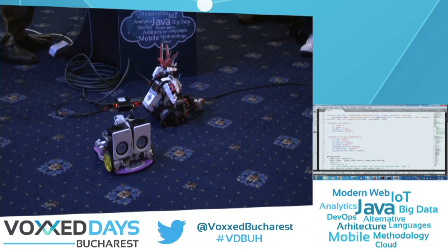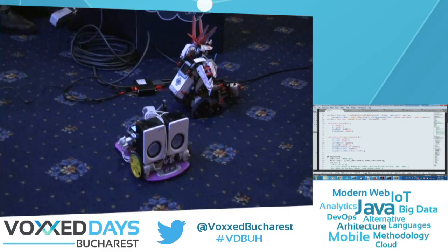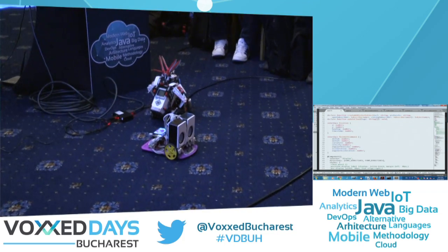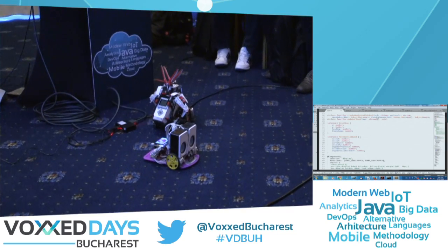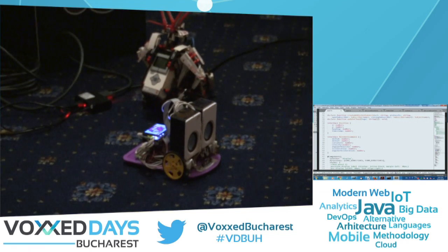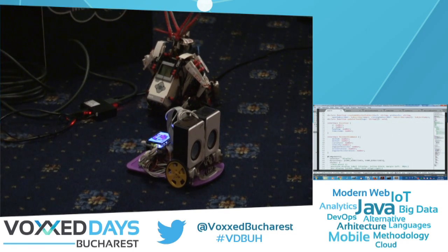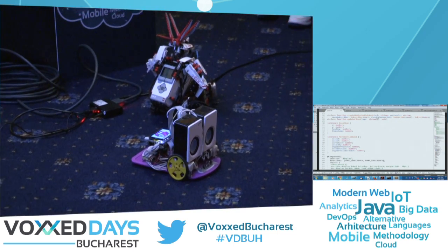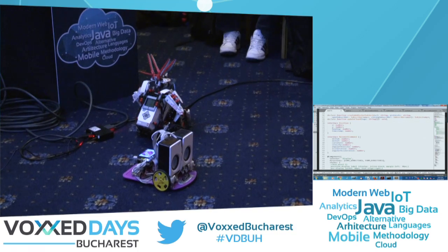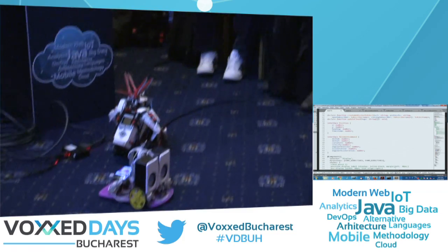First of all, this robot uses some hardware, which are modified motors with custom-made optical encoders inside of them. So that's why one motor is faster than the other one. But this is actually good because this gave me the idea and the need to make an adaptive odometry implementation. It took me 2 or 3 days. All the papers have some incompletenesses or some mistakes, and all the formulas should be checked. But I think I can demonstrate now. So let's go to the demonstration.